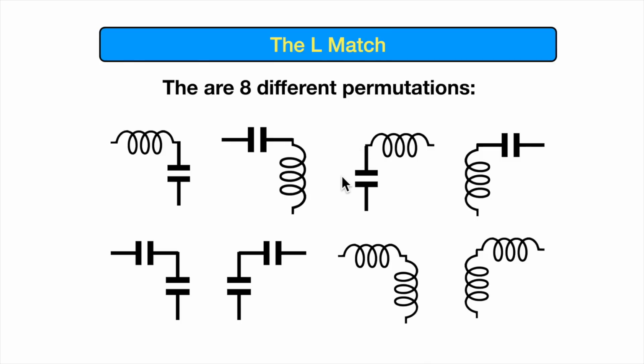So you won't be surprised then to know that this design and this design are in fact high pass filters. So here's your capacitor, which will allow the high frequencies to pass through relatively unattenuated, and here, shunting to ground the lower frequencies, is the inductor. So this is a high pass, and just the same, a high pass with a larger impedance this end, a high pass with a larger impedance this end.